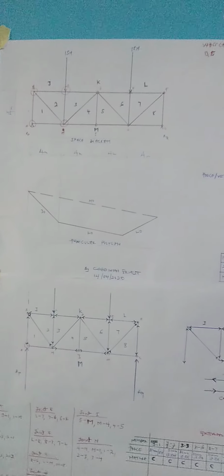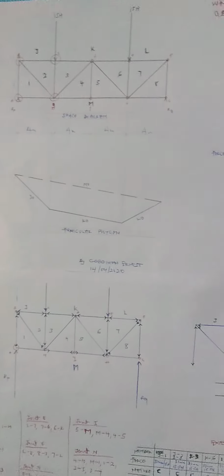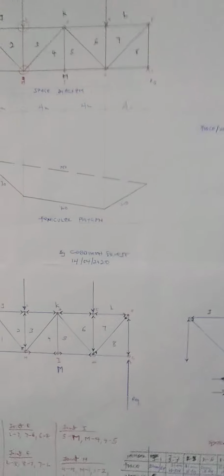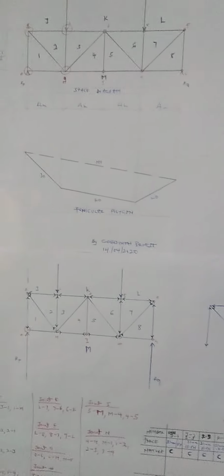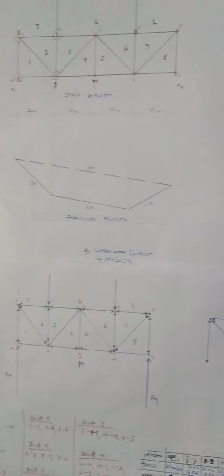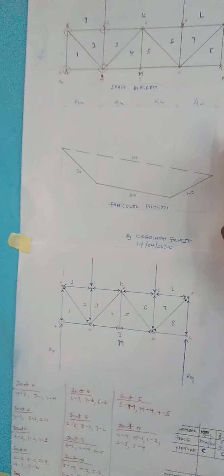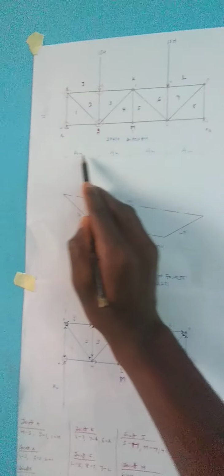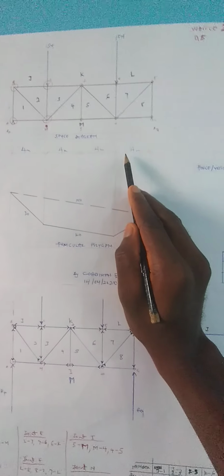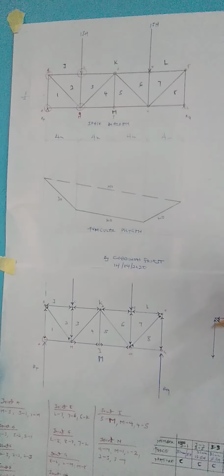So 4 meters will be how many? It will be more, so let's divide. 4 divided by 0.1 will give us 40 millimeters. So the 4 meters in each space will now be 40 millimeters so that it can be constructed or drawn on the sheet of paper.